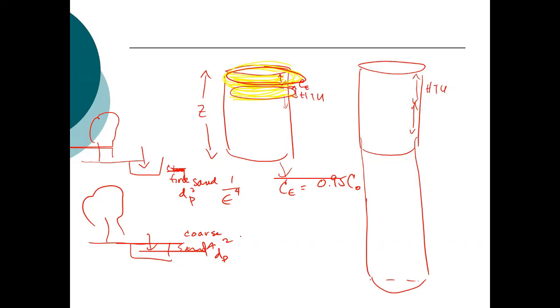So the smaller the particle, the greater the head loss. So if I go to powdered activated carbon, which is a really small particle size, I'm going to have a very high head loss, which means I have high pressures in order to push the water through that column. So you'll never see a column with powdered activated carbon. You'll only see powdered activated carbon added either as a batch or a continuous system, for instance, adding it with the coagulant. Does that help?